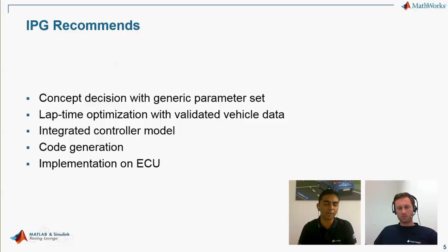They can see how far they can go in optimizing the car to get the best lap time out of it. There is a predefined environment in CarMaker by which you can ask the IPG Driver to do lap time optimization. I don't know how many expert users are aware of this. If you're not aware, probably you should try it out. There is a special module available in IPG Driver to do lap time optimization.